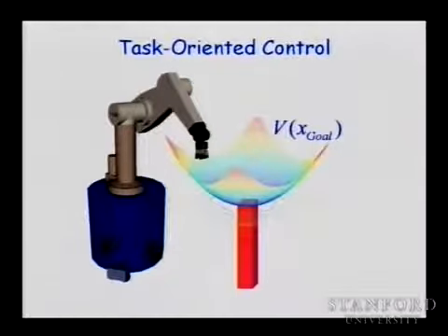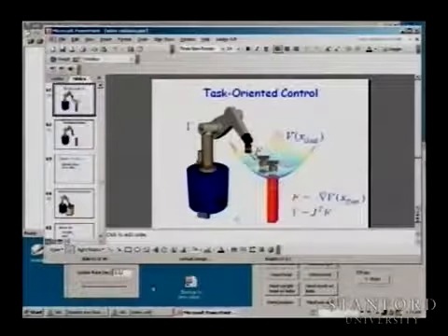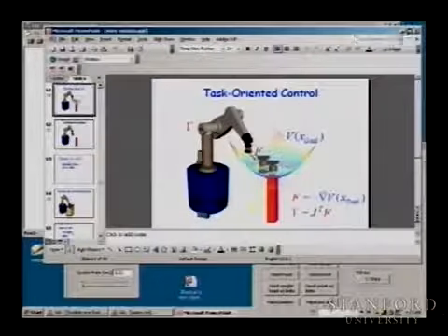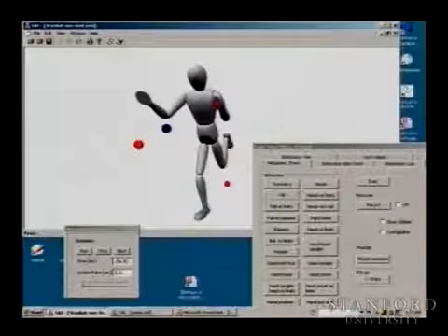And at the initial configuration, you have no commitment about the final configuration of the arm. You are just applying the force towards the goal, and you are moving towards the goal. So simply by creating a gradient of a potential energy, you will be able to move to that configuration. And this is precisely what we saw in the example of this robot here.